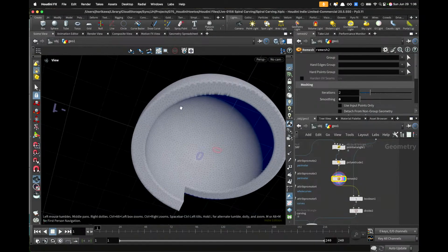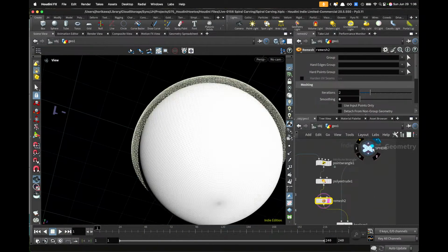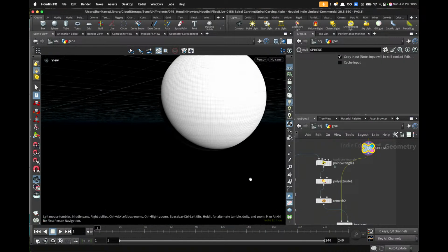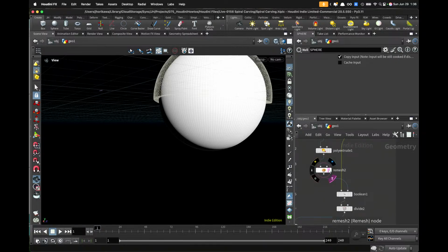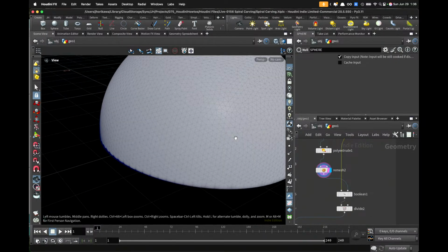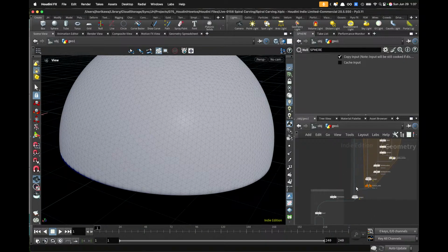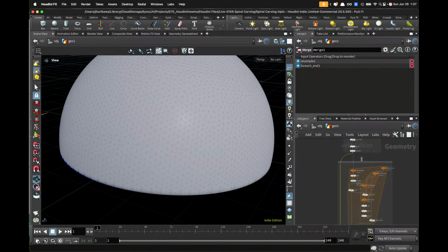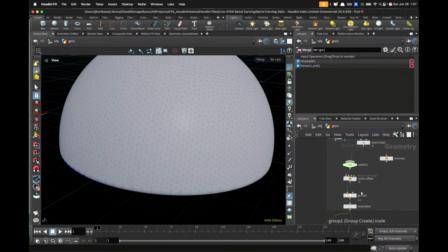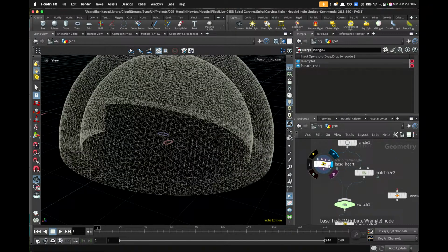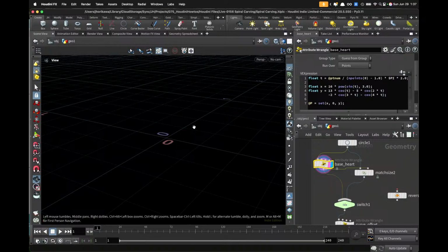So this thing is being used to trim the sphere. That is because the normal direction is upside down. That's the reason. So it's going back to this process. The reason why it didn't work is because of the face direction.